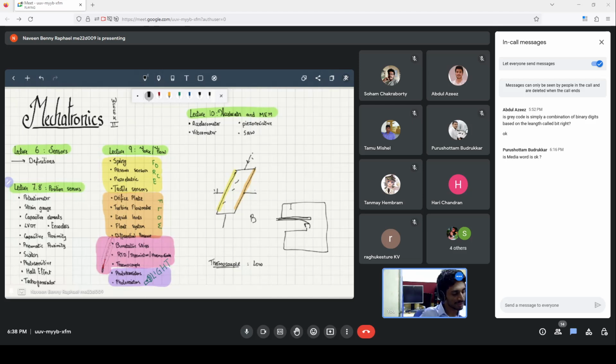Yeah, so the output is different, right? The piezoresistive sensor changes resistance, and that's a more constant output. Changing the resistance suddenly will not necessarily change the dynamics of the electrical circuit. A piezoelectric system, on the other hand, gives an output of voltage or charge, if you like it that way instead. So they have different uses.